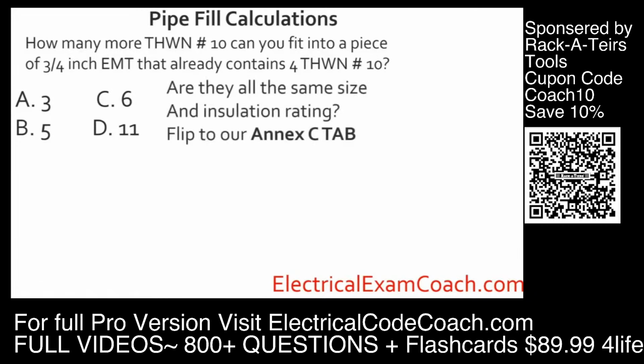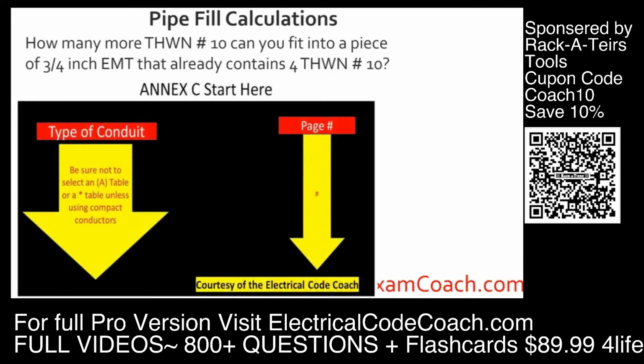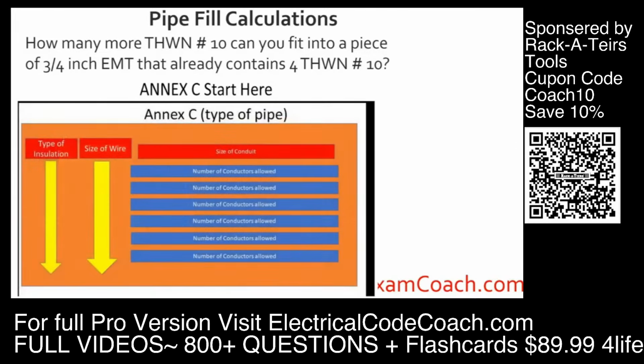The first thing we're going to ask ourselves, are they all of the same type and insulation? They sure are. So let's head to Annex C. When we get there, we're going to start on the left-hand side and find our type of conduit, being sure not to select an A version of the table. Then we cross over and find our page number. When we get to the actual table, we're going to read the black bold heading to make sure we're in the right table. Then we're going to find our type of insulation under the insulation column, find our wire size, and then come across the top to our size of conduit and tee off with our answer.